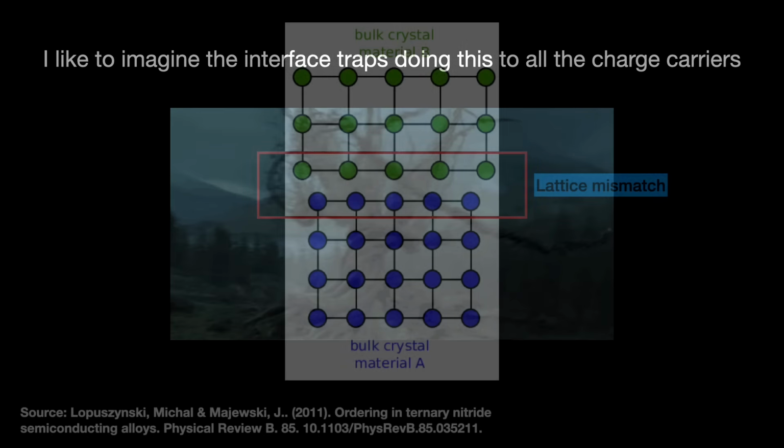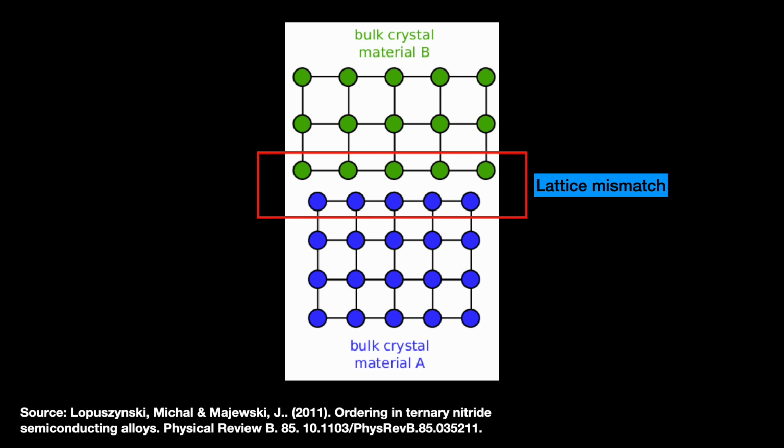Pure silicon and hafnium oxide do not match well together. Like incompatible Lego bricks, there are lattice mismatches. Moreover, the silicon substrate surface will have dangling bonds left over from cleaning or patterning. Growing the silicon dioxide fulfills these dangling bonds, calming them down, or passivating them. The amorphous silicon dioxide also acts as a buffer between the silicon and hafnium oxide.